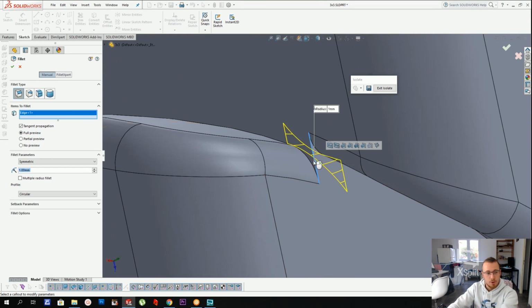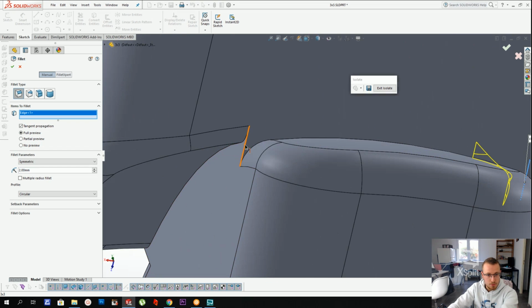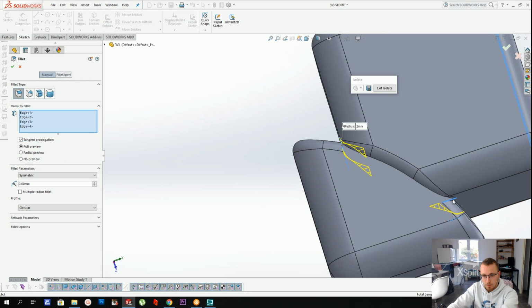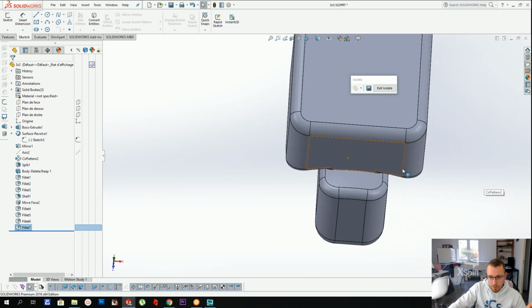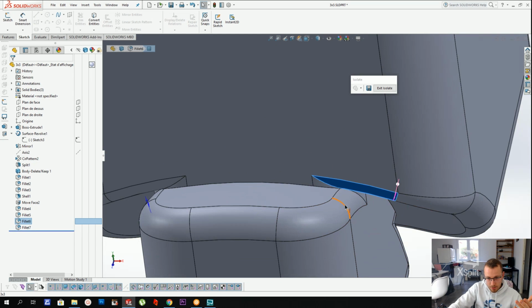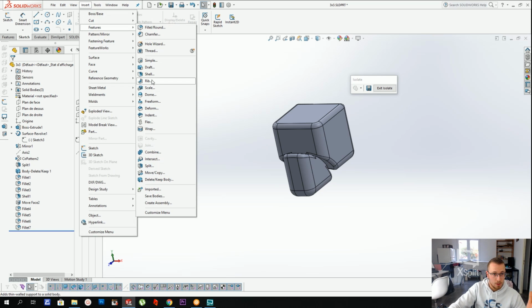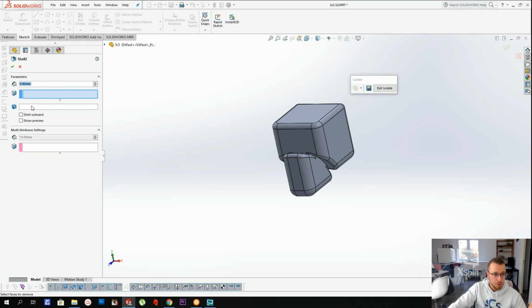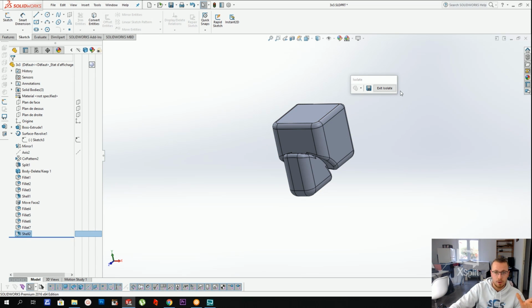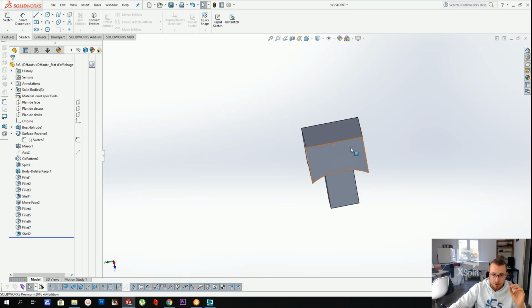Sharp edges are your worst nightmare as a puzzle designer, so let's just use any fillet size. Those don't really have much influence, but you still want to remove them, so let's just remove those. And now you've got these rounded edges right there, these ones, the part is perfect, you just need to hollow it out. So you use the shell function, again 0.8, choose the solid, click the solid, press enter, and you've got this hollow part.